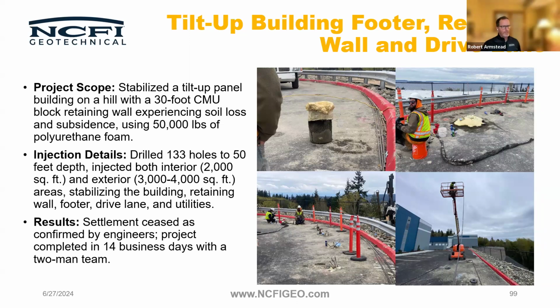What precautions would you take with void filling under asphalt? You need to be deep enough. You can lift asphalt. You don't have to just void fill, but you can't lift the asphalt itself. You have to lift the soil underneath the asphalt. So you need to make sure that you're deep enough in a circumstance where you have a non-structural topping covering over what you're injecting. It's usually 3 to 5 feet for lifting asphalt. You might get away with 2, but I'd be looking at an average of 4 feet.